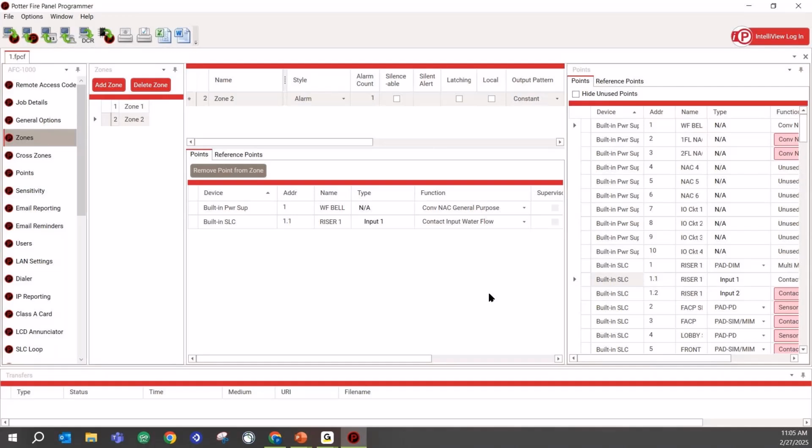Number 2, most often, we try and put that appliance right behind that riser on the exterior of the building. So this offers the fire department another piece of actionable intelligence. More often than not, the fire department is going to turn the sprinkler system off when they arrive on the scene. That protection process has already started, and they're generally going to turn it off.